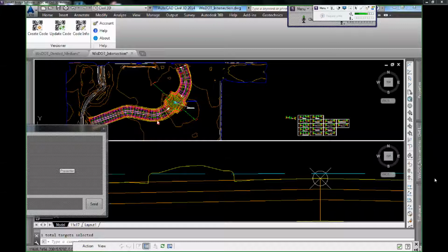Another one is the overhang correction. And it's because overhang correction is using link definition to re-establish surface triangulation differently than if you had just used the feature lines alone. It's causing a discrepancy between the location of the longitudinal break lines, which are our corridor feature lines, and the surface and what it's doing.